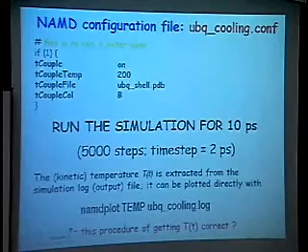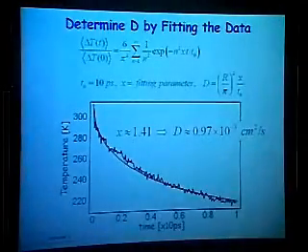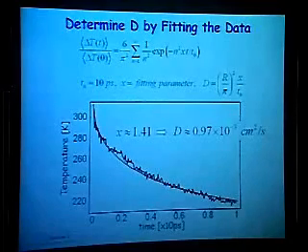If, however, you want to make absolutely sure, you can do the calculation yourself. You can extract the velocities from the DCD file for the inner atoms and just simply calculate the corresponding kinetic temperature, and you will see that this is exactly what NAMD outputs for you. So NAMD does quite a lot of work for you, so it looks so simple using it and running it, and therefore it's a really great MD program, and also is very fast and scales very well.